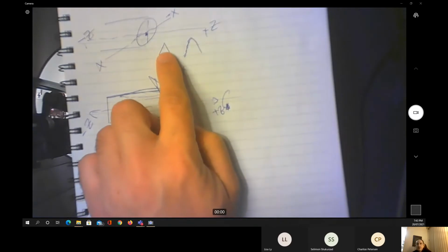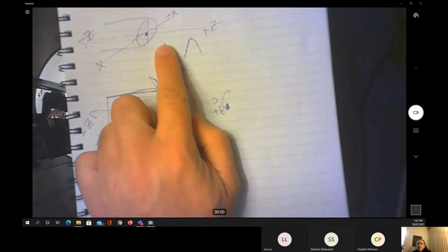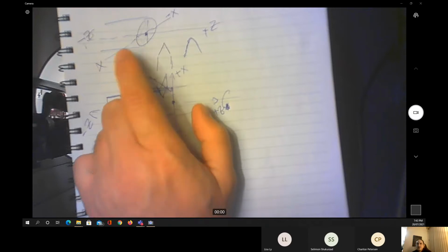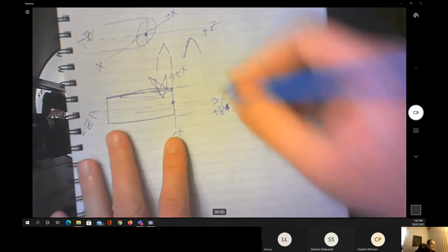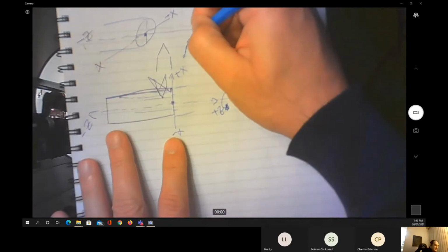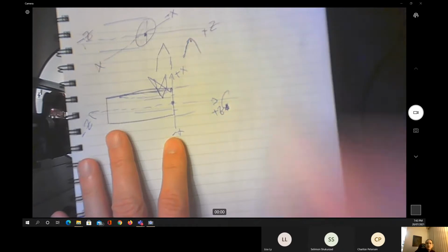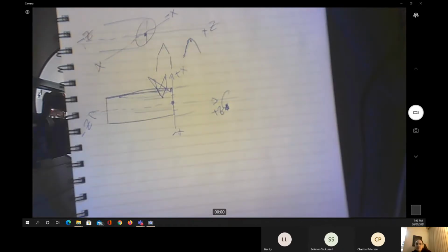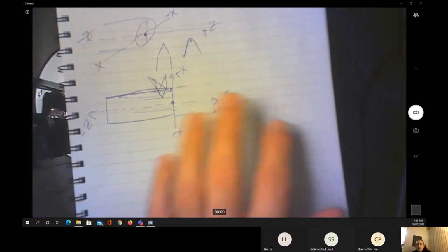In the case of the high-speed steel with the sharp nose, we don't have to do that because the contact is going to be directly with the work. For the other one, as I told you, the contact is going to be here. So we need to consider the offset later. We do the compensation for the arc. It's something like when we do the offset in the case of the turning operation. Basically, I'm not going to do that because you can simply write down the full code without any compensation or the offsetting for the cutting tool.